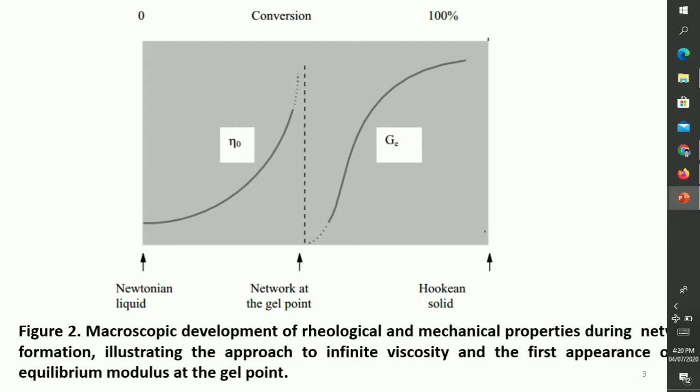Dynamic mechanical analysis is especially well suited to characterize supported samples from pre-gelation, or gelled unsupported samples, to the completion of cure as well as fully cured thermosets.